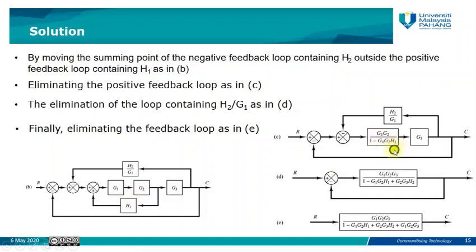So this is the block diagram, the new feedback system, the equivalent transfer function of the feedback. And this new transfer function now is in series, or in cascade, with the value of G3. So these two can be combined in cascade. The new transfer function will be G1, G2, G3 over 1 minus G1, G2, H1.